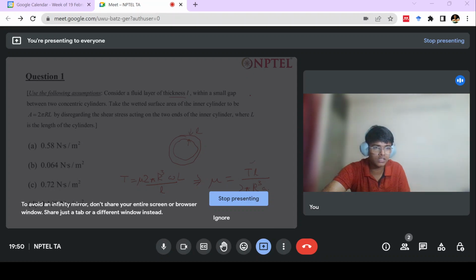So we can set the RPM and calculate the electrical power that the shaft is consuming, and from there calculate the mechanical work done with this torque and omega. Given the power and the RPM, we can find out the torque. So this can act as a device for measuring viscosity.